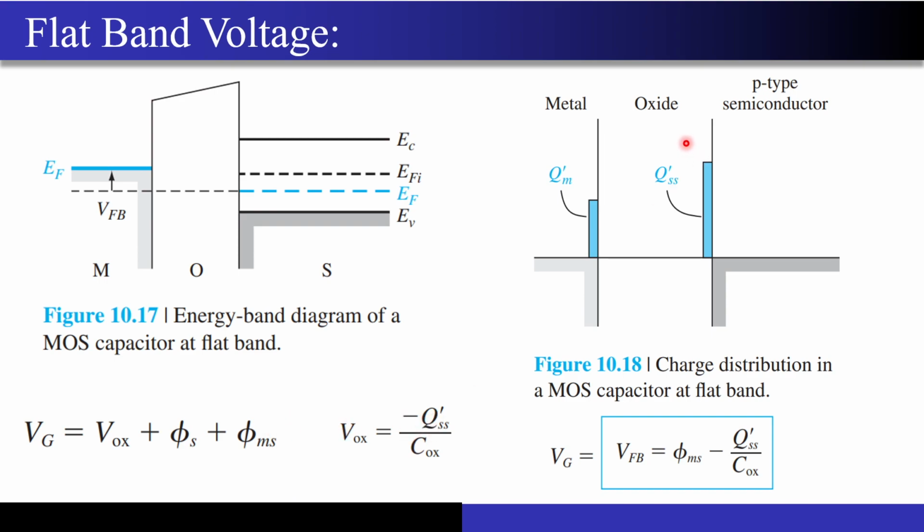And now we also said, hey, the moment you try to fabricate this MOS structure, let's say the TSMC, the Taiwan Semiconductor Manufacturing Company, is assigned a task to fabricate this structure, there will be some impurities in the oxide, right? So this is what we were saying. And the moment there are some impurities present in the oxide, then they will have some net charge density, right? Assume that this is a positive charge density, and this is a p-type semiconductor. Let's say I don't apply anything at the gate, the moment I have positive charges inherent in the oxide, they will be pushing the holes that are near the interface into the bulk. So inherently I will have some depletion region present over here,